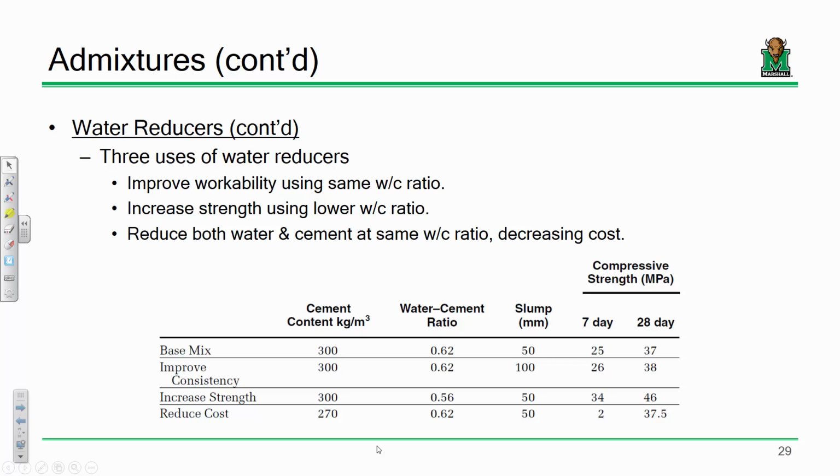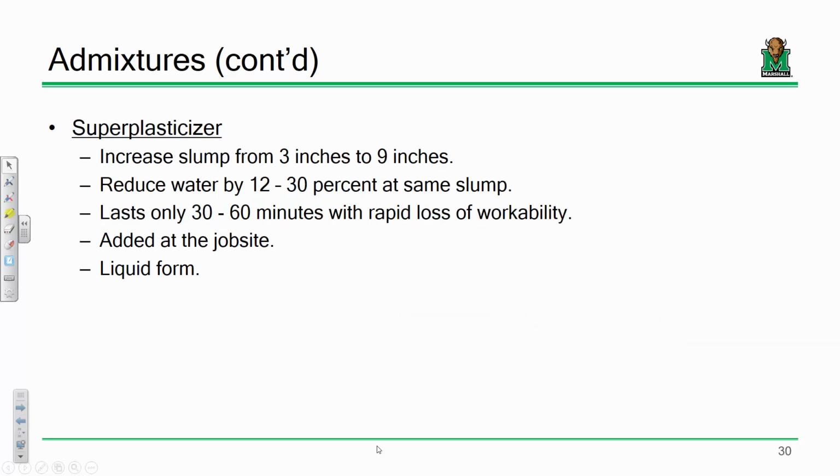We are actually going to have some water reducer in our mix number 2. So we're not doing that in mix number 1. I want you all to essentially use regular old concrete for mix number 1, and mix number 2 will spiffy it up a little bit. We'll use some self-consolidating concrete, so it's going to have some different cementitious materials, some water reducer, and some stuff like that. So just to give you kind of an idea. Okay. So on super plasticizer, it can really increase your slump. Because you're getting that same workability, you can even decrease the water content a little bit.